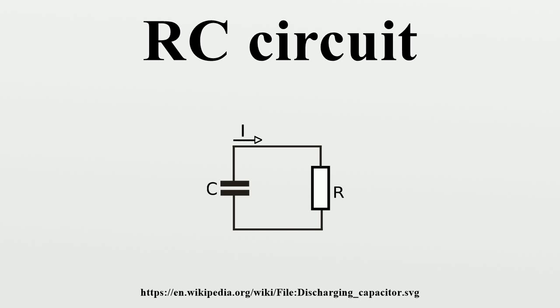Frequency domain considerations. These are frequency domain expressions. Analysis of them will show which frequencies the circuits pass and reject. This analysis rests on a consideration of what happens to these gains as the frequency becomes very large and very small. This shows that, if the output is taken across the capacitor, high frequencies are attenuated and low frequencies are passed. Thus, the circuit behaves as a low-pass filter.